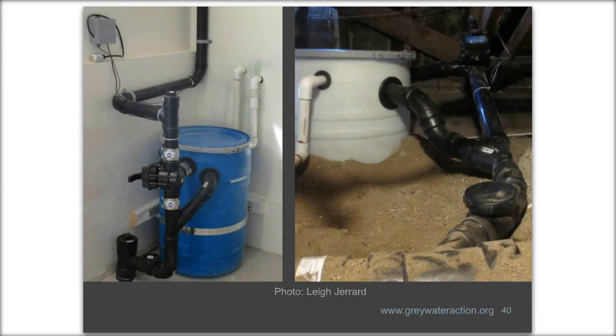Here's some pictures. You can see the picture on the left. That is in a basement. The gray water is coming down, going into the tank. There's an overflow that connects back to the sewer, and then the water is pumped out.